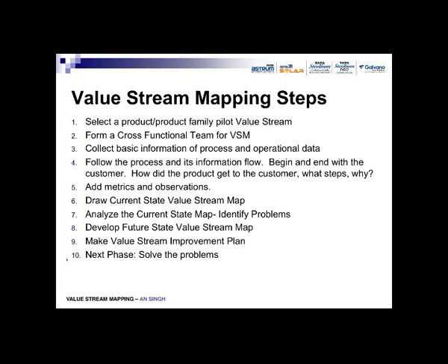Based on the data analysis and observations, the problems which result in the generation of waste are identified. Then the same group, applying the lean tools, finds out what solutions can be made to eliminate those problems. Based on that, once the problems are solved, how will the value stream look? As you have seen in the process of paper stapling, earlier it was a 5-step process, and operations were carried out at 20 feet distance, and the layout change was made and everything was redesigned.